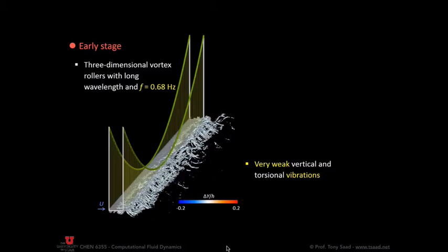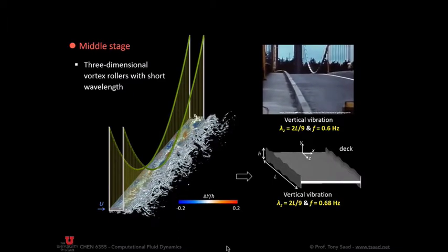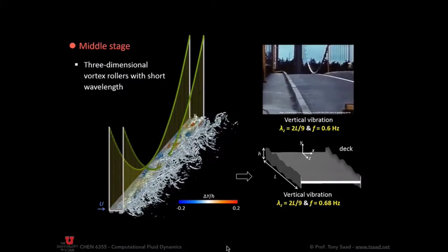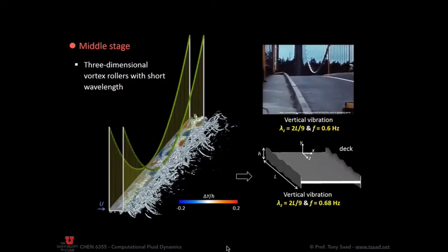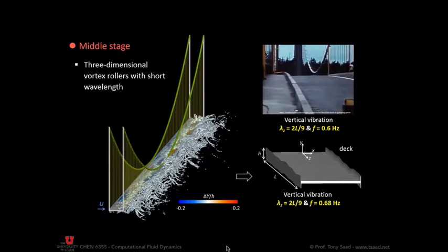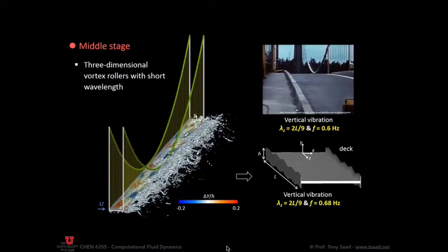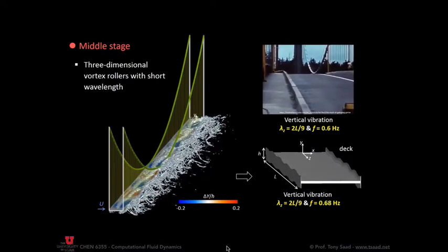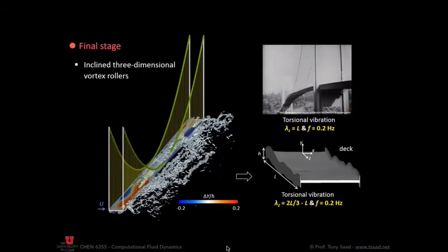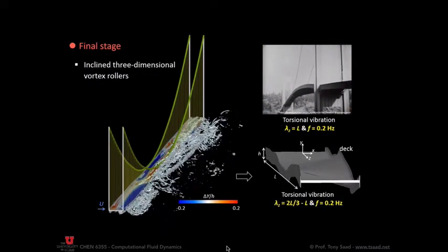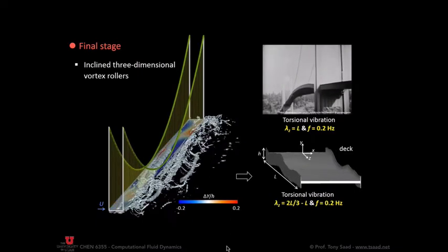Now, as these vortices are developing, they are creating a fixed frequency. Now, see the colors on the bridge. Those are describing that wave, longitudinal wave, up and down. And then, after a certain point, as the forcing frequency starts resonating, you start creating the lateral vibrations. So this is just to show you that this is doable. Now you start seeing the vibrations, the transverse vibrations.